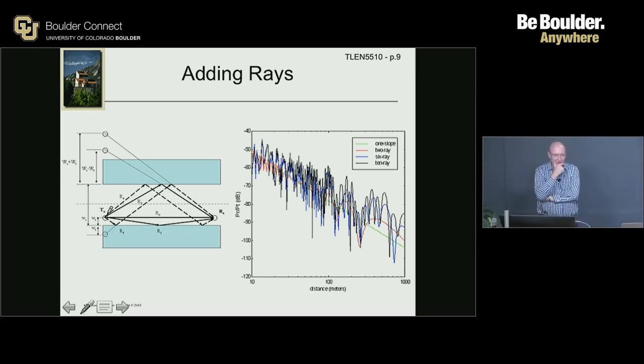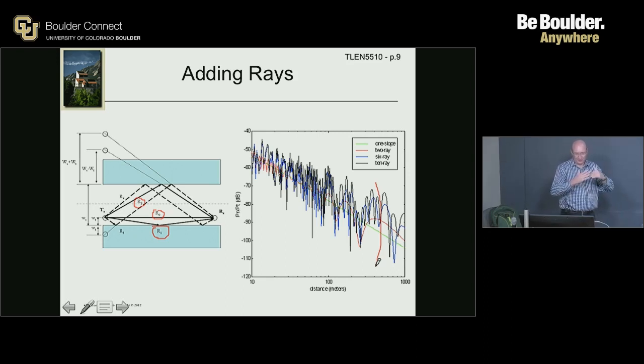I don't know how to answer that. That critical distance is really only defined for the 2-ray model. It's right there, you see the last hop of the 2-ray model. We know that after that distance, there will never be a deep fade anymore. But on multiple rays, there are many fades, and we usually use the same critical distance to say that on average, the envelope is 1 over d squared, then 1 over d to the fourth.